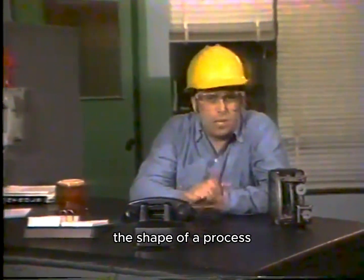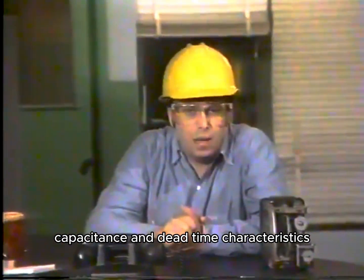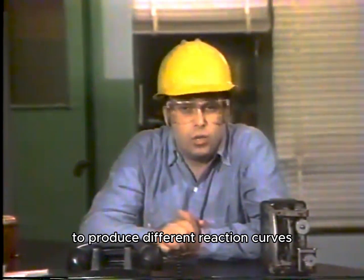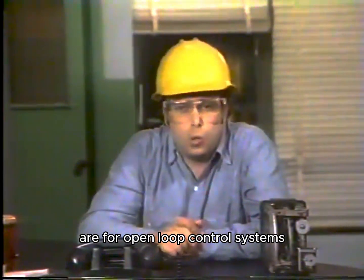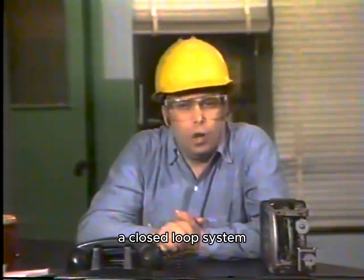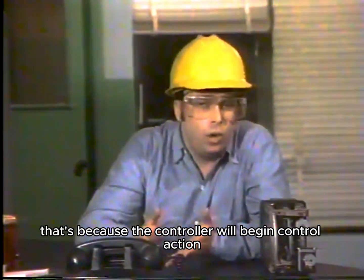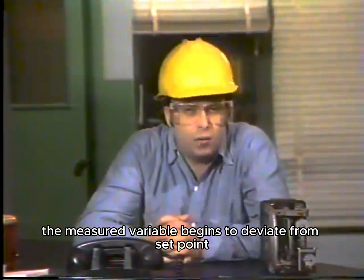The shape of a process reaction curve during its response time is determined by the process resistance, capacitance, and dead time characteristics. You can expect different types of control systems to produce different reaction curves. The reaction curves that we've seen up to now are for open-loop control systems where the controller is in manual or hand. A closed-loop system will produce a different reaction curve. That's because the controller will begin control action as soon as the measured variable begins to deviate from set point.